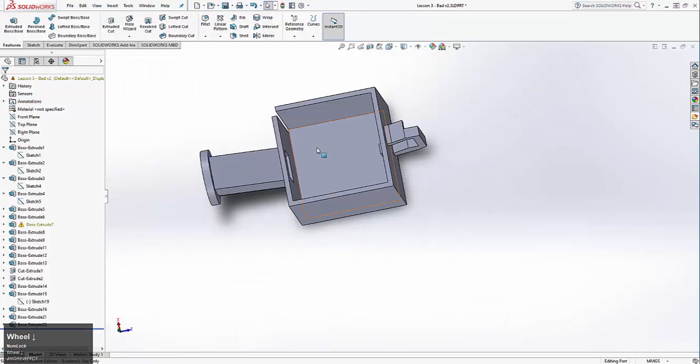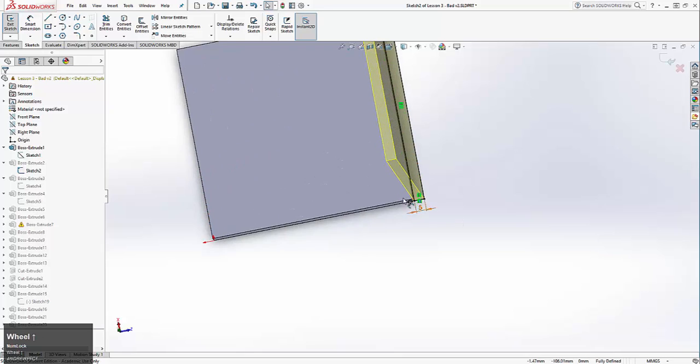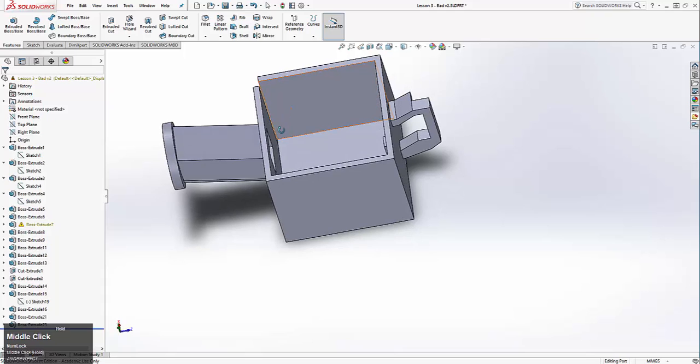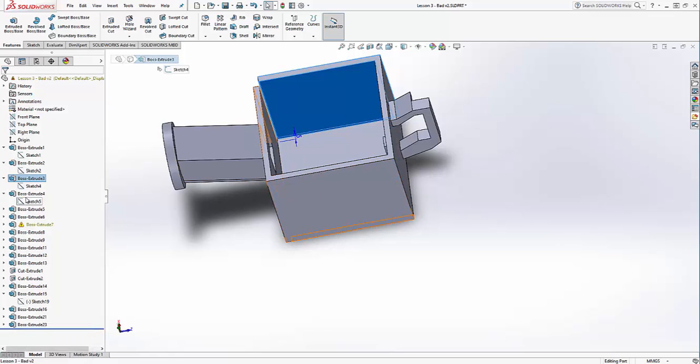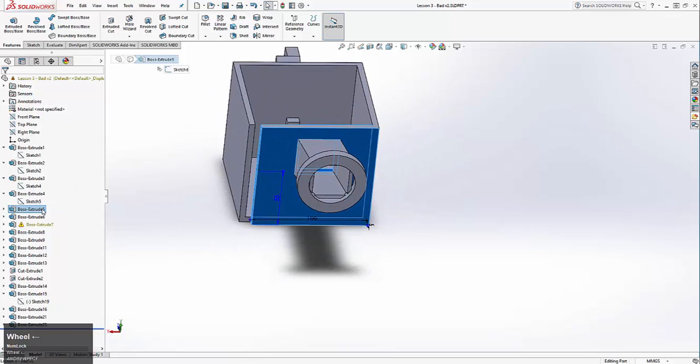That's why the original base was 90 millimeters, because I wanted the outside to be 100. And with each side being 5, that's how you would get that. So 90 plus 5 plus 5 is, yeah, anyway. So this one's 5. If you wanted to change the thickness, once again, you'd have to go in and change every single part, or every feature. So this one has a 5. This one, instead of it being in the sketch, the extrusion is 5 wide. This one has a 5. This one as well.